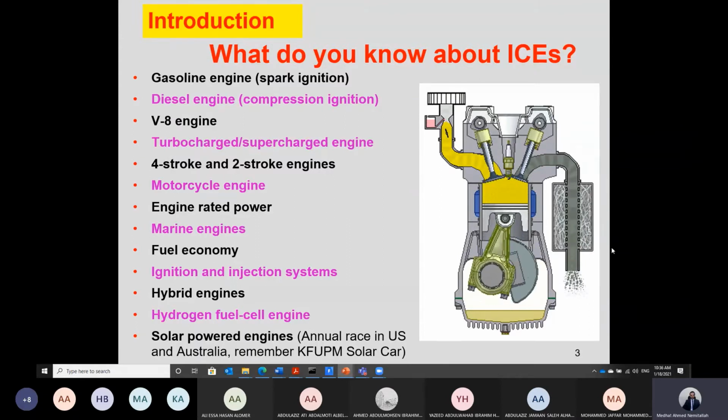If the piston moves up, while moving up for the compression, it also has the intake stroke. Then we have the spark plug, then the expansion, and at the end of the expansion stroke, we have the exhaust stroke. So the engine completes the cycle in 2 strokes. Inshallah, we'll be talking about the main differences between the 4-stroke and 2-stroke engine by the end of this chapter.